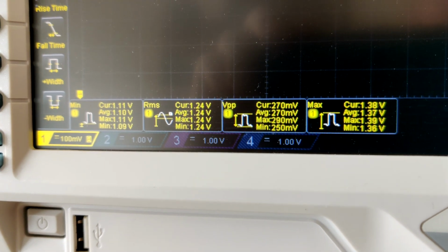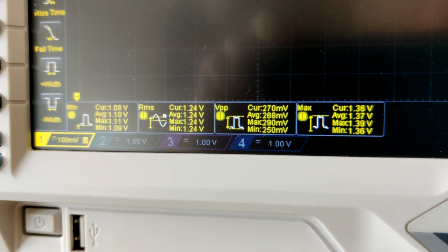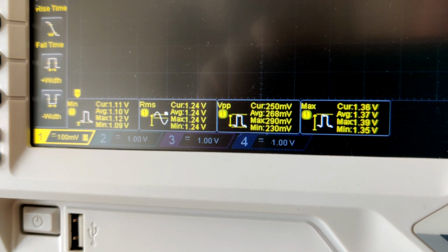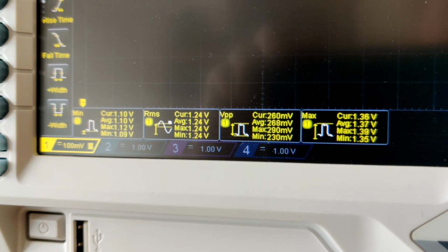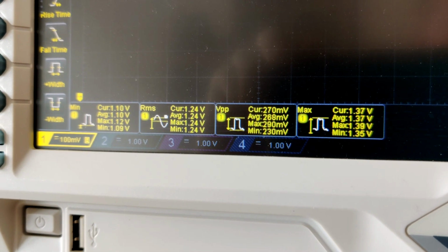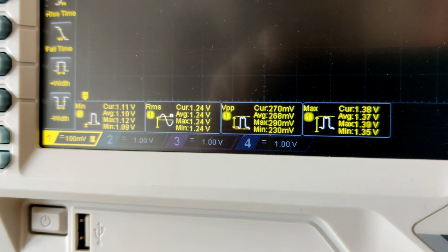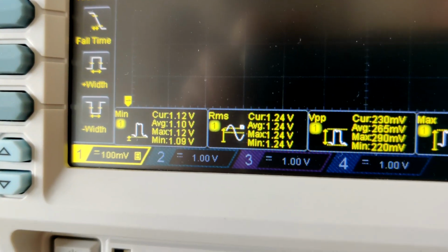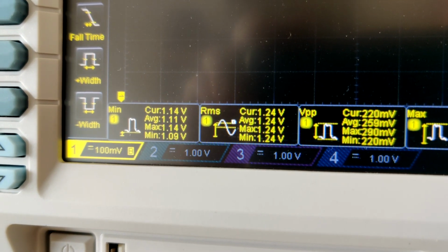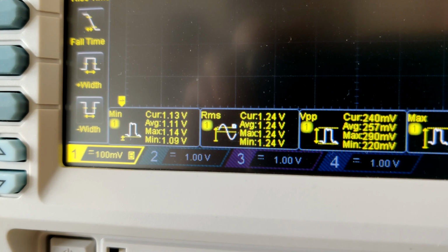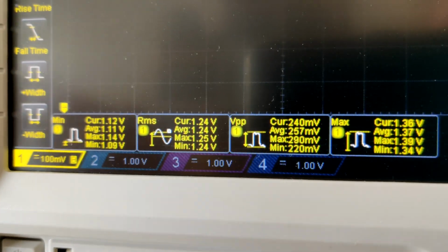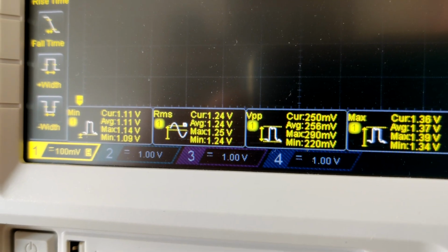And now you can see, oh, VPP is really bad. Like that is really bad. So our average is 1.24 volts, actually slightly above what we set, but that's probably just because my measurement hookup is not the best. It should be actually slightly below 1.213 volts. But you can see we are losing quite a lot of voltage. That's about 120 millivolts that are just gone from my average. So yeah, the card's using as much power as a 480 at 1.24 volts.